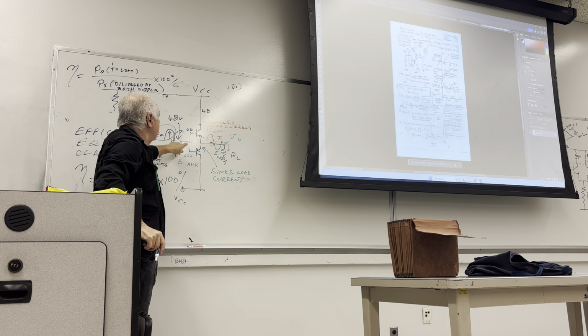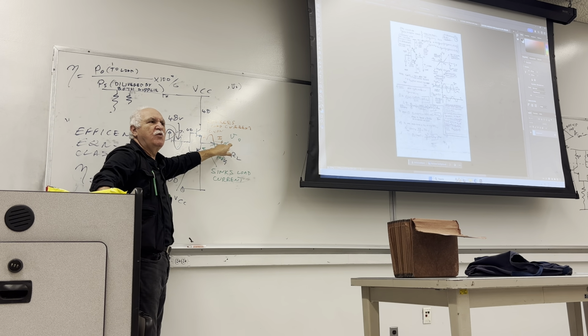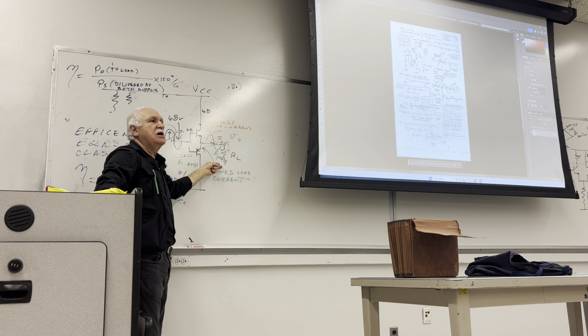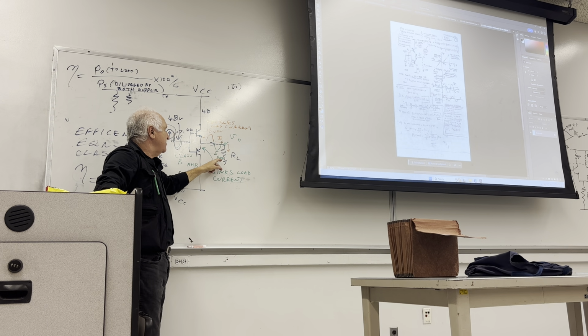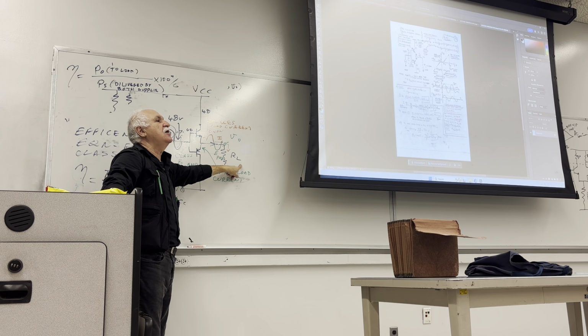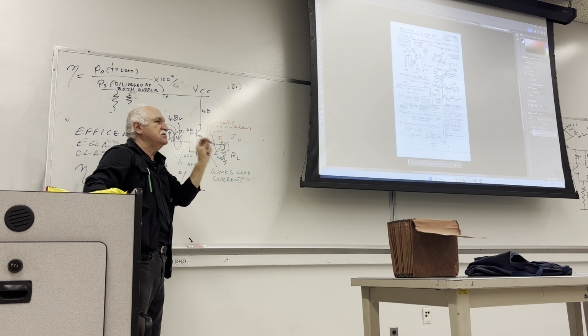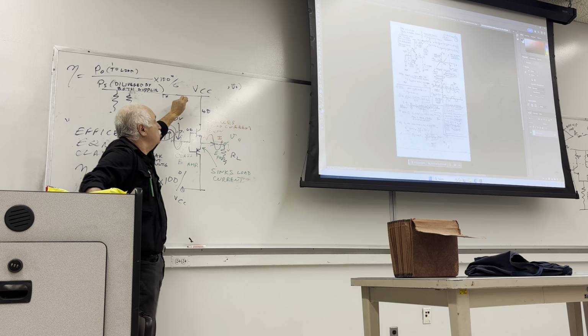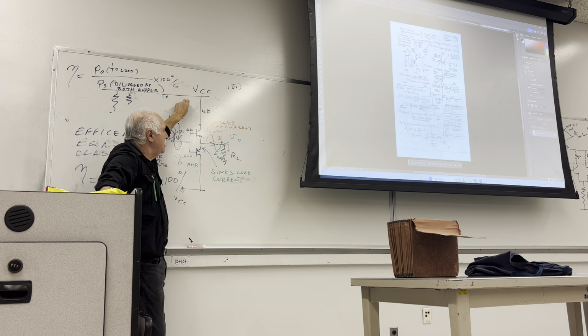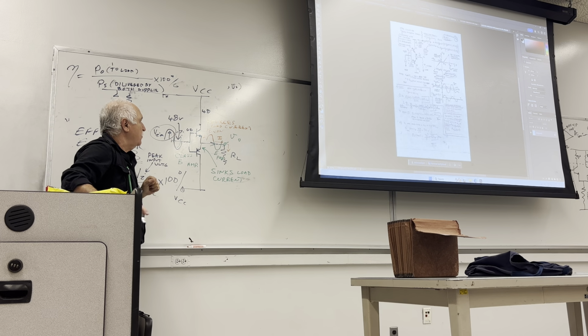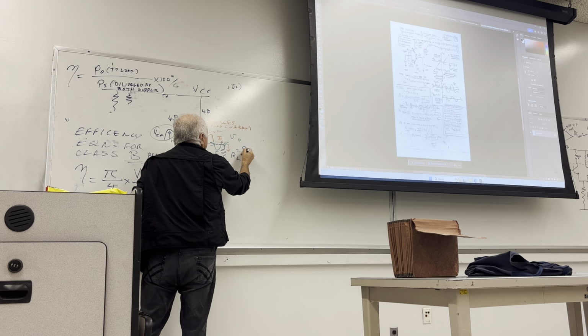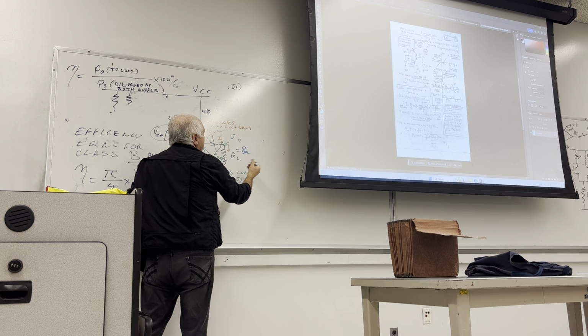So 48 is the maximum here, approximately maximum over there. Then you can calculate how much power will be there. 48 over radical 2 will give you the RMS. RMS divided by 8 ohm, if it is 8 ohm, will tell you how many tens or hundreds of watts it is. So you can design accordingly. Choose your power supplies accordingly to deliver the power that you want in here. For example, this is an 8 ohm. We've got an 8 ohm speaker. I need a 100 watt speaker.